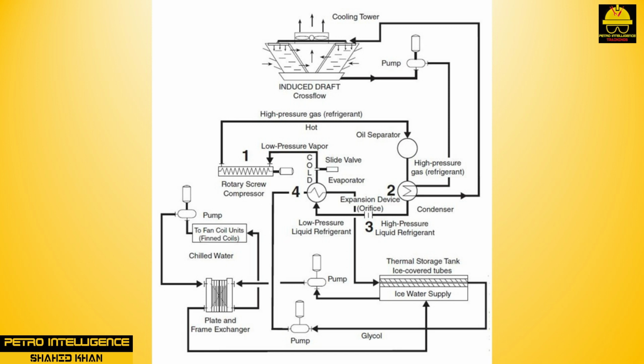Propylene is a good example of such a liquid. Its boiling point at atmospheric pressure is -54 degrees Fahrenheit. Propylene is normally a gas, but using a compressor can liquefy it. In compressing any gas, work is done, and heat is generated in the gas. In compressing propylene, we add heat to the gas and raise its temperature.